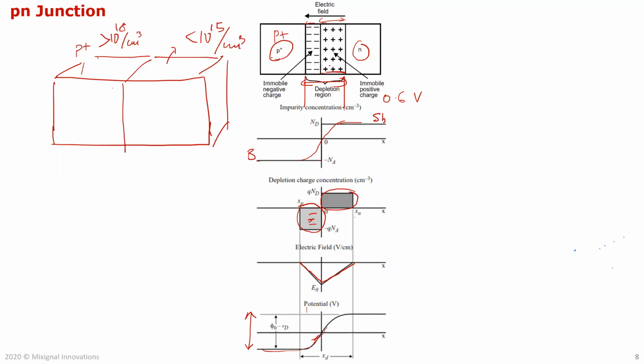Now these are obviously balanced, because whatever electron goes from the N to this side leaves the same positive charge. But the number of carriers it lodges with is a lot more for the same volume here than in this, just because your dopants are a lot thinner here, so it will take more unit volume for the same charge.